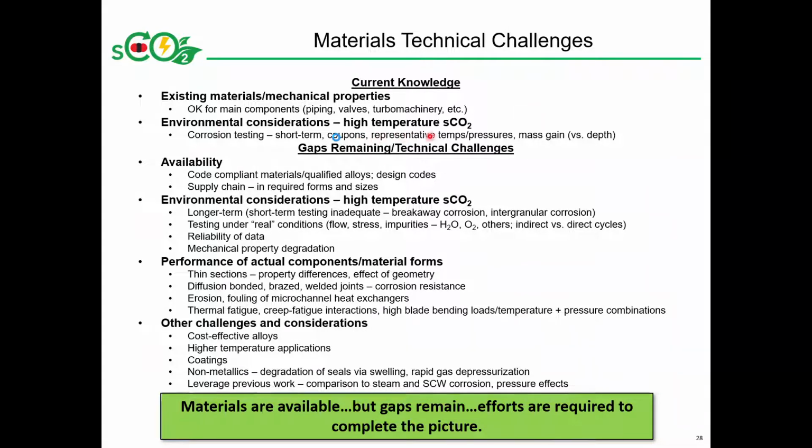The representative temperatures and pressures that we would see in various sCO2 cycles have been covered by the testing, and the results for the most part have been presented as mass gain versus actual corrosion penetration, that sort of thing. So we do have a pretty good idea of what's going on here, but